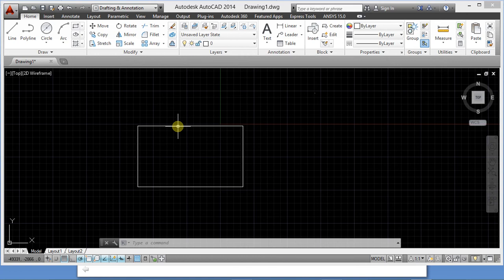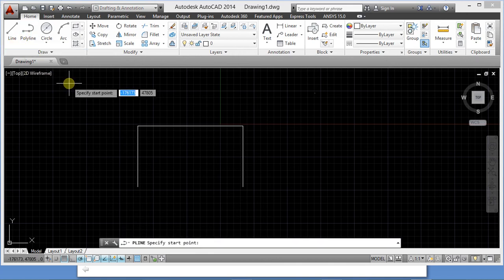Now to show you what I was trying to do, if you click this line, this is line too. If you form a sketch closed with line, it will show you different lines separately. If I select this one and delete, only that line will be deleted because it's a line. It's four lines that complete that loop. Unlike in polyline, a polyline is a group of lines all connected to each other.